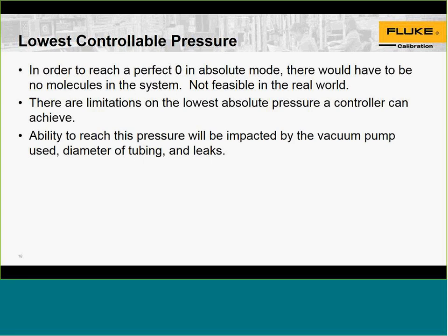On the lowest absolute pressure a controller can achieve, the vacuum pump, the tubing diameter, the length of the tubing, leaks, and devices that are hooked up to the controller will impact that.